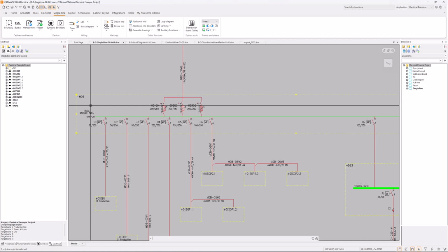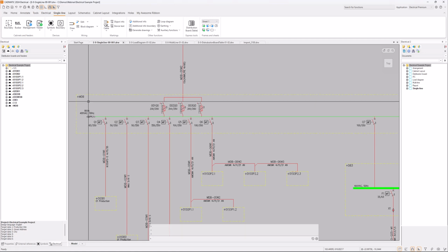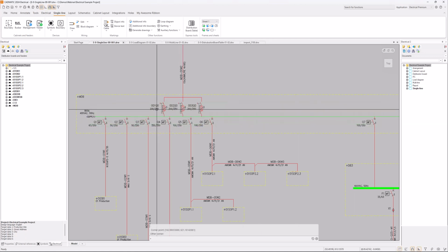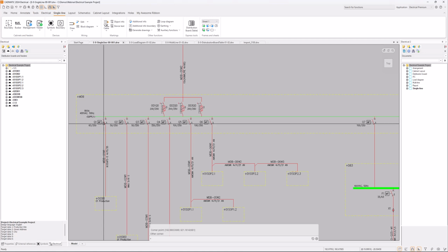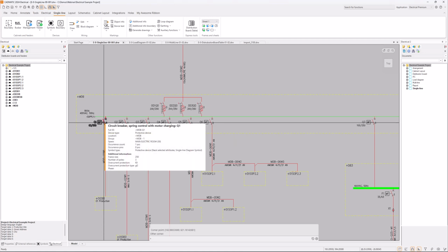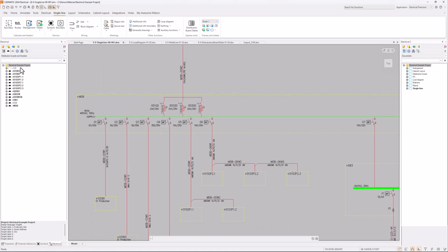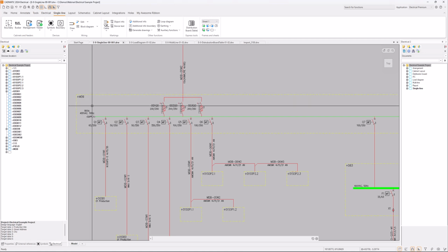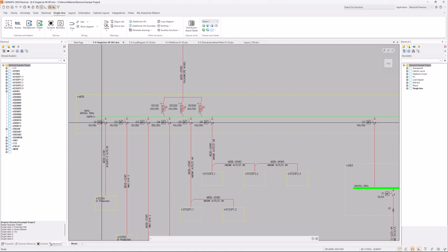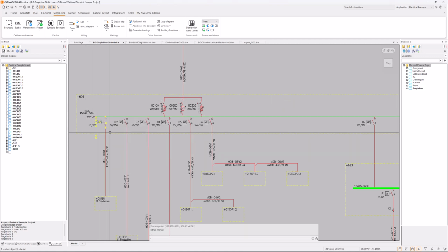Now this is a boundary object which will combine all these things inside here, all the protective devices, for example, here, they are already pointed out to be part of this MDB. So whenever I have a boundary and I insert something inside it, it will automatically be part of this main distribution board.